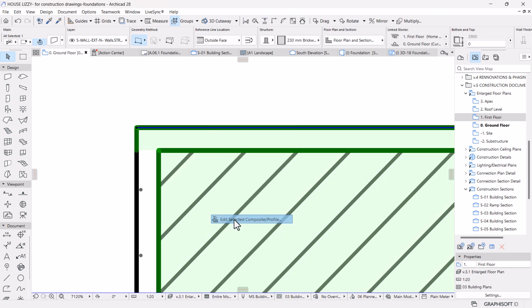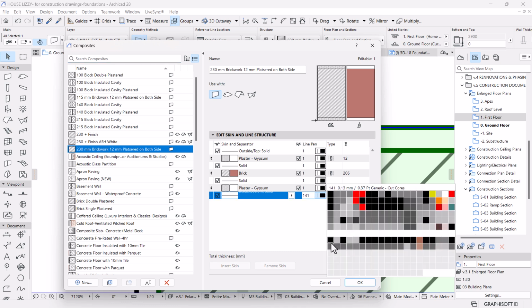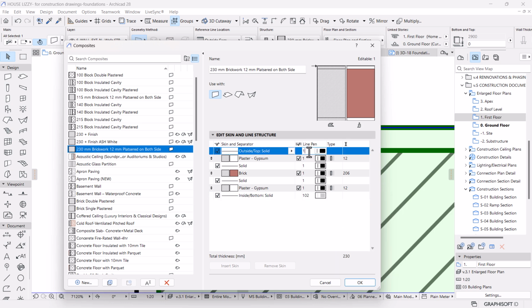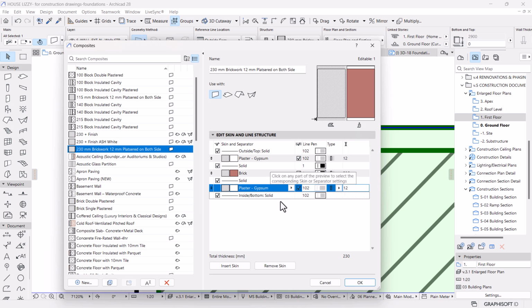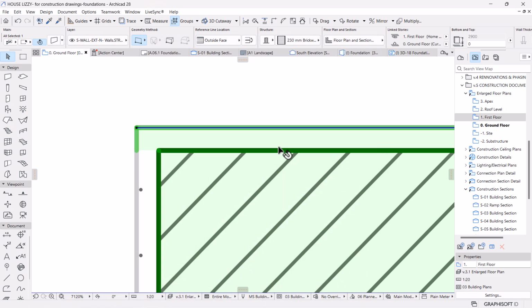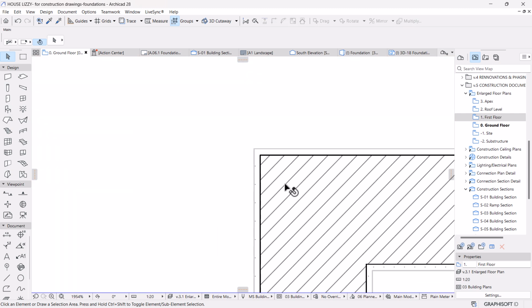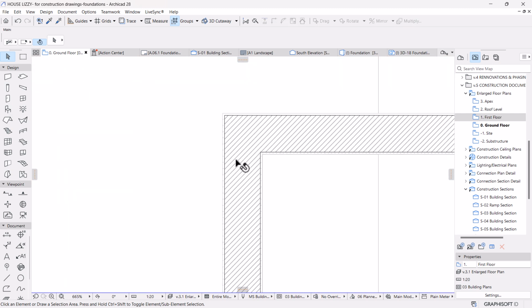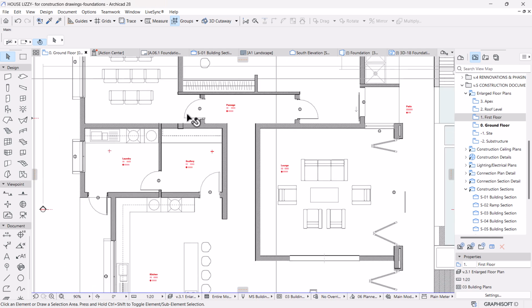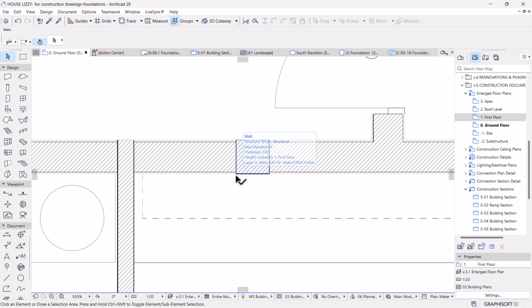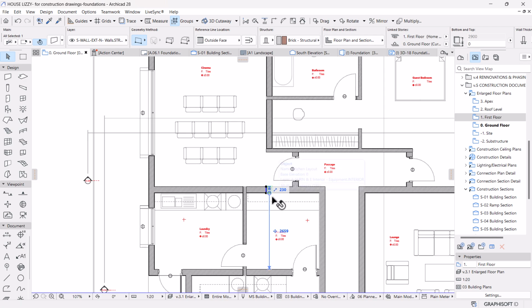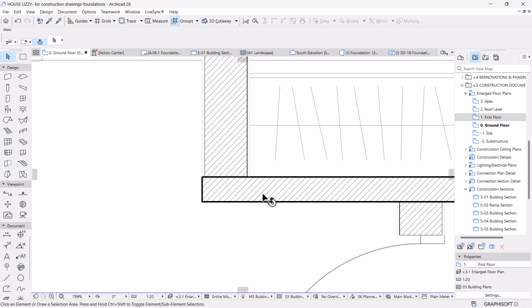I'm gonna select this, right click, and so the plaster would go for a lighter pen, 0.13, which is pen 102. Should do the magic. I'm gonna select both of that like so. So that's basically what I wanted. This is the outline for the core brick. So I'm gonna hit OK. So that will be addressed. All right. Why is this wall here? I'm gonna delete.